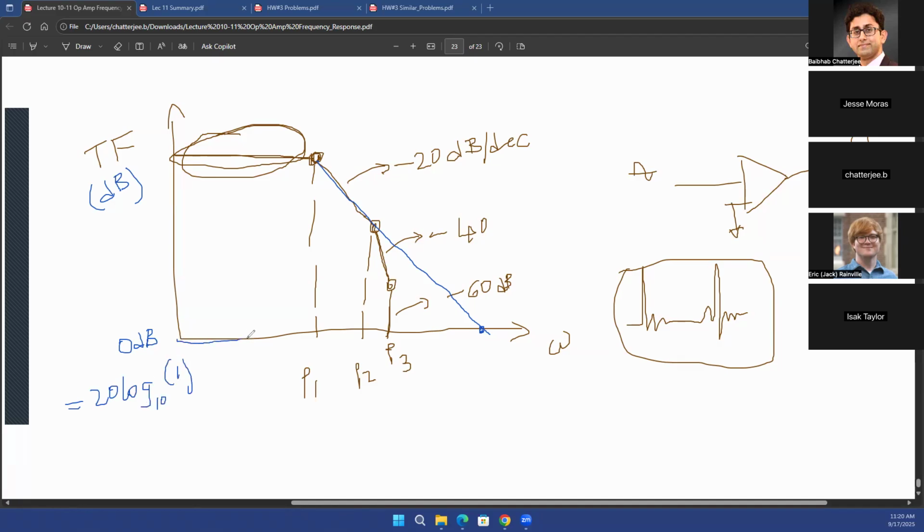So if your x-axis is the 0 dB point, and you had a first order system, that is, you have one pole only, and you are reducing the gain by minus 20 dB per decade after that first pole, you'll cross your frequency axis at some point. That frequency is called the gain crossover frequency, or GCF. Again, we'll come back to this later.